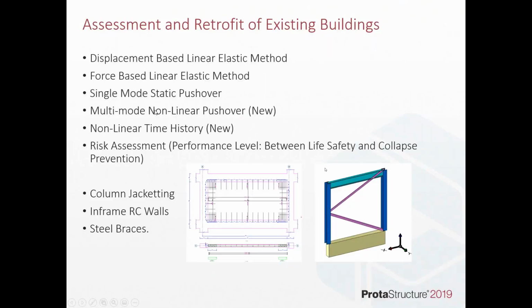Another thing that I haven't really touched on today is the assessment and retrofit of existing buildings. This is really looking at performance-based design of both existing and new buildings. And we have different approaches for this. You could be doing displacement-based or force-based, single or multimodal, and non-linear time history and pushover analysis can be performed. Based on the level of requirements that you're trying to satisfy, if it's a new building, there may be immediate occupancy categories that you're trying to satisfy. We can check that against the code.